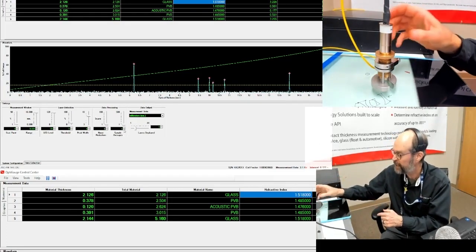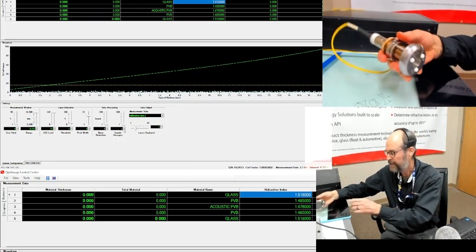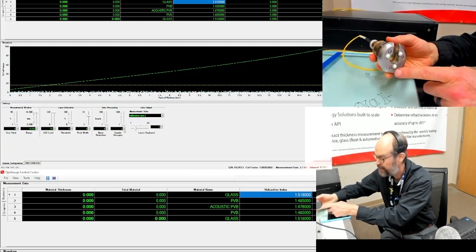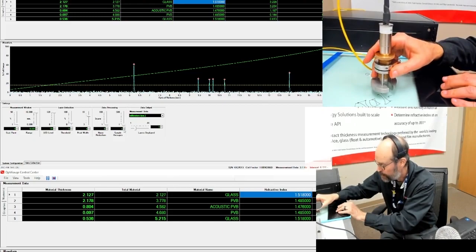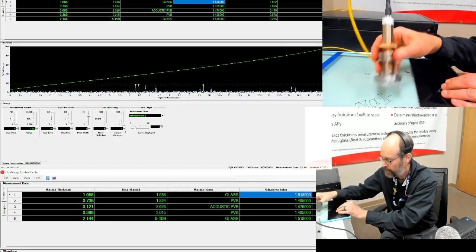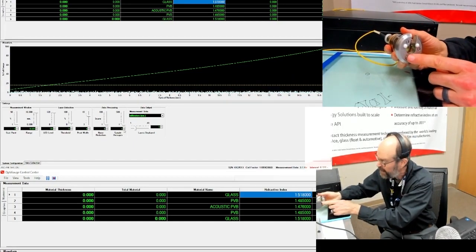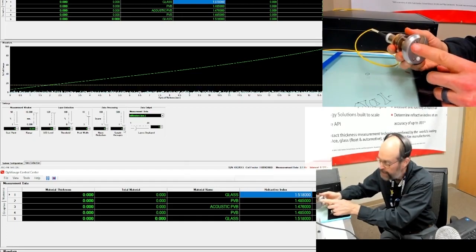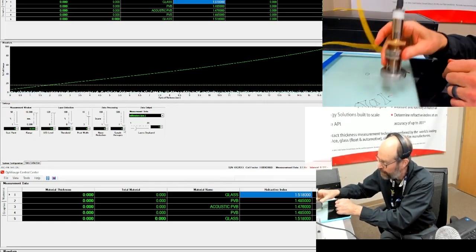There is no tip and tilt here, but in fact there's kind of a hidden tip and tilt. These 3 white balls are what sets how square the probe is to the measurement surface. So keep an eye on these 3 white balls, make sure they don't start getting flats or dented or worn out.